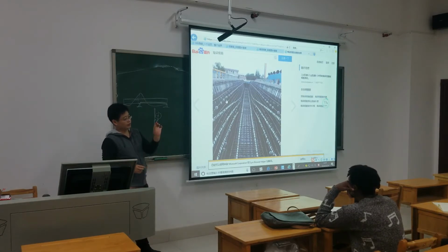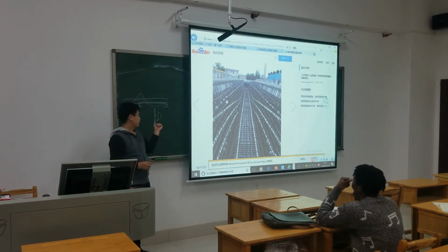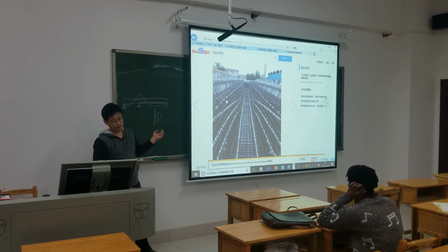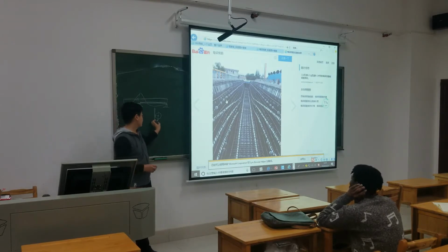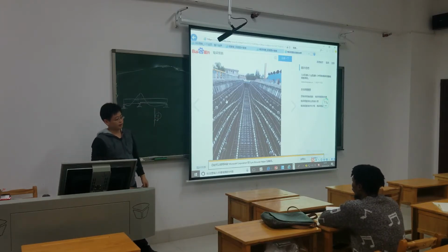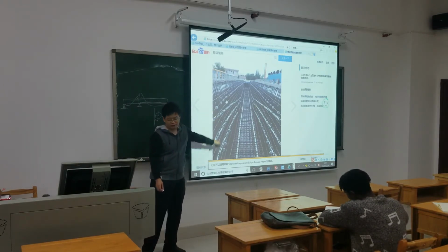If the cover thickness is too thin, the steel bar is easily corroded, affected by wet weather or other factors. So we need enough thickness to protect the steel bar. That is the meaning of this block.